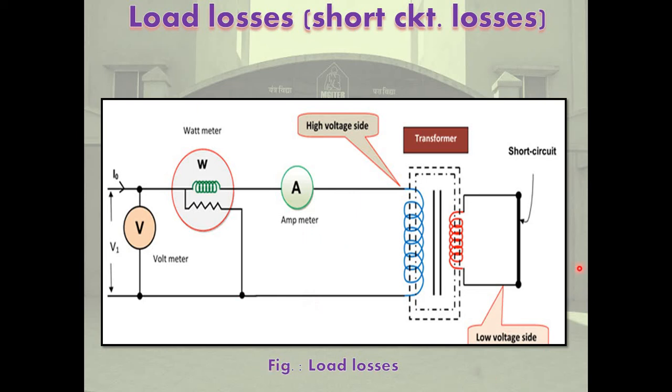The short circuit test reveals the various defects in conducting circuit like wrong positions of the conductors in the windings, breaks and fractures in the parallel conductors, the use of conductors of wrong section or bad contacts, etc.